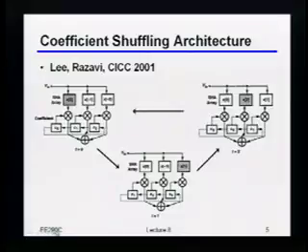And those analog delays basically end up being some sort of sample and hold circuit, which then end up causing either distortion or power, because you have to make sure that your noise is sufficiently small, and so on and so forth. So what we then started talking about was other ways you could build FIR filters in the analog receive domain. You could do it on the transmitter too, of course, but it doesn't really make too much sense. Basically, you just try to avoid these long analog delay chains.